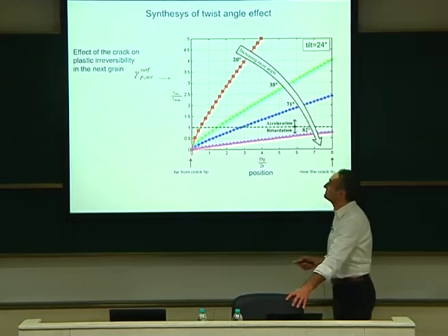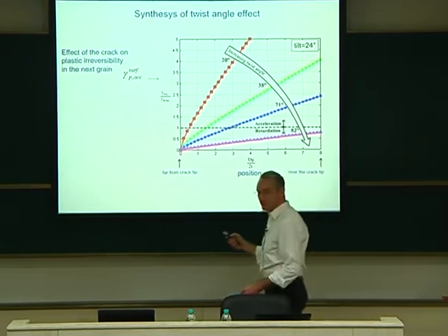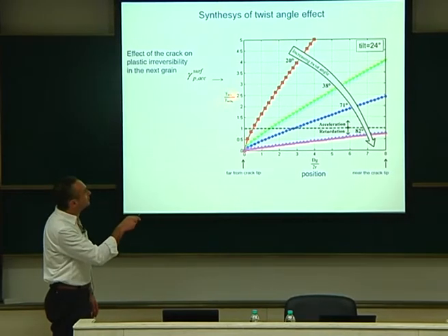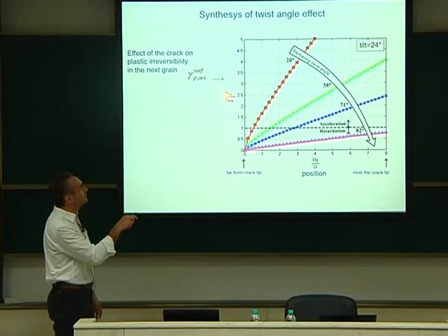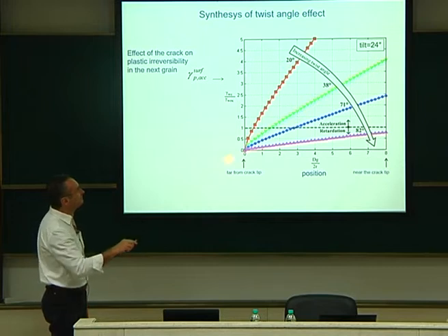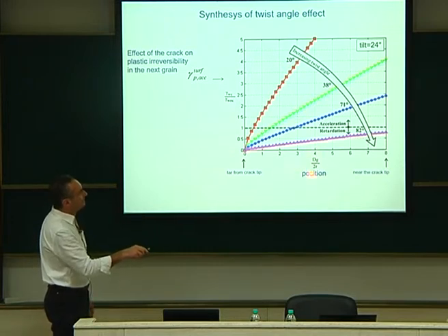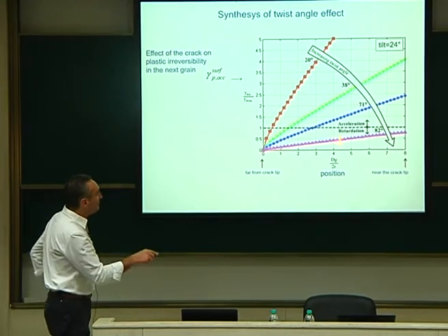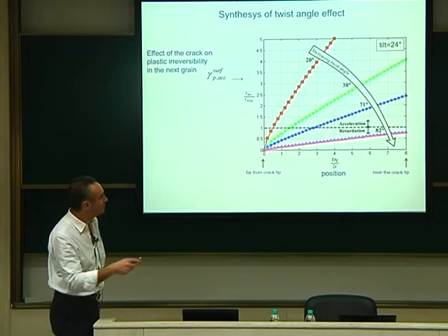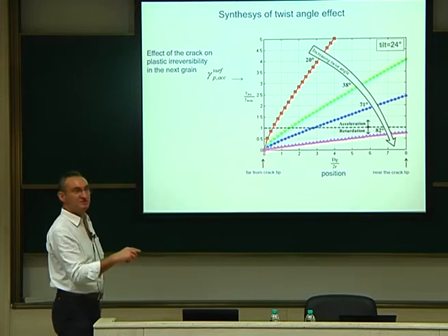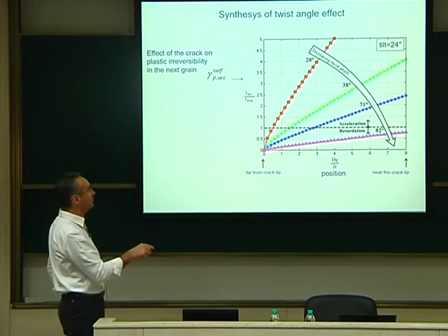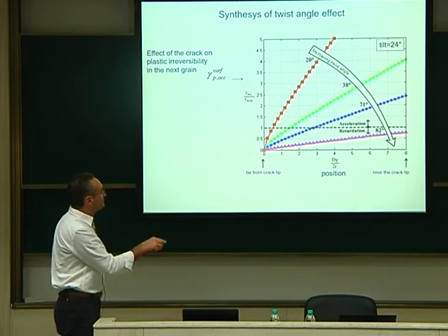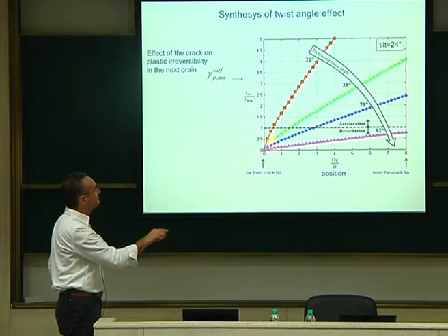So the conclusion on this study was the following: we compute the irreversibility parameters with a crack and without a crack, so this is the ratio with crack and without crack. This is the evolution of this ratio depending on the diameter and the position of the crack, like this. So we have several possibilities. We have some places where, because of the crack, advance is slowed down. So it means that the crack is limited because of this orientation. In some other cases, it will increase the irreversibility. So yes, it will speed up the irreversibility like this. So it means in that case, it will be nefarious.